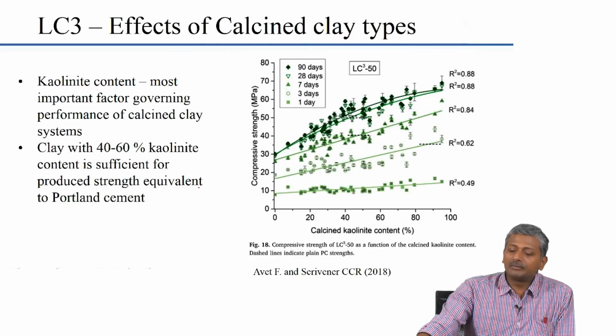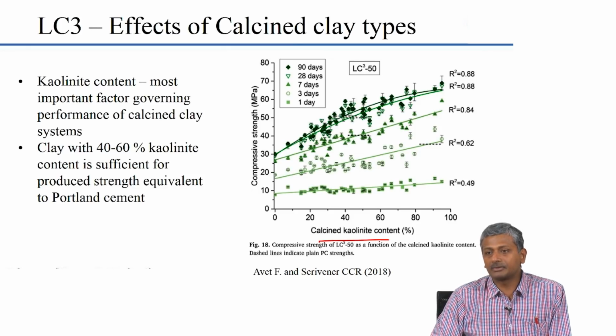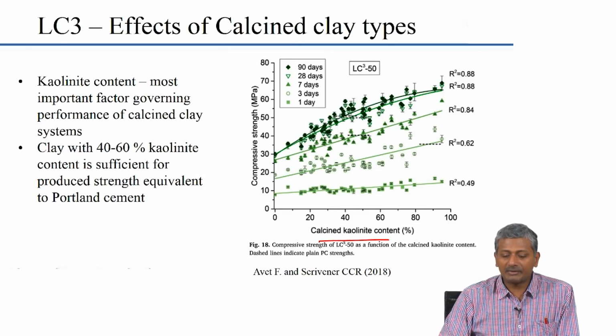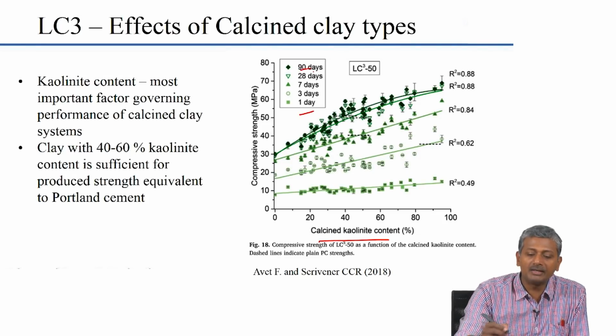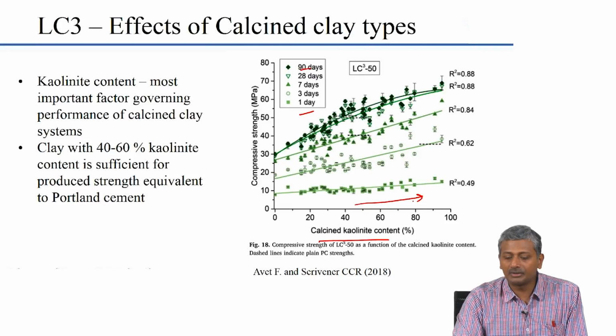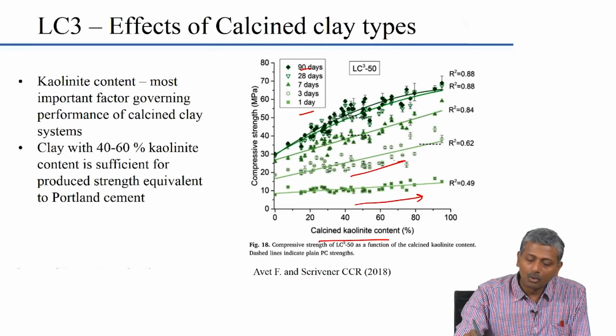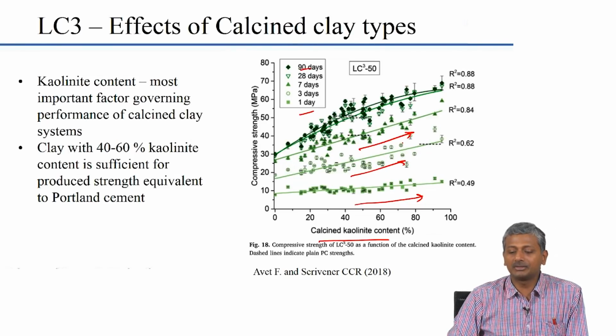Okay. So, here in EPFL in Switzerland, where the primary research on this material was done, they also tried to understand the effect of the calcined kaolin content on the performance of mortars, okay, in terms of the compressive strength. So, they have these figures for 1 to 90 days of strength. So, if you look at the 1 day strengths, there is definitely a benefit of increasing the levels of calcined kaolinite content. Obviously, more the kaolin, the better the reaction, and you get a much better performance with respect to higher levels of kaolin.